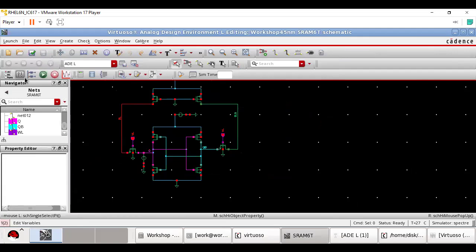It simply means that whatever potential is coming from here now has an easier path towards ground. Means these two transistors have become better conductors. Means increasing the width has improved the conductivity.